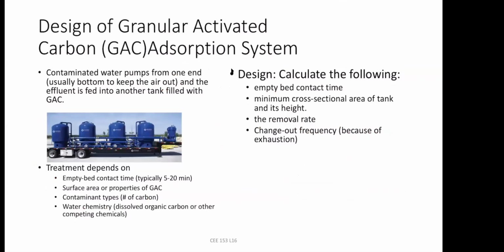So what we are going to discuss today is carbon adsorption techniques. The technique is very similar to what you learned before for any adsorption of pollutants in soil. This is the same concept. The difference is you use activated carbon. Why is it called activated carbon? Well, think of how activated carbon is being produced. We'll discuss a little bit more, but just know that you take this activated carbon, put it inside this blue tank that you see over here, just fill the tank.